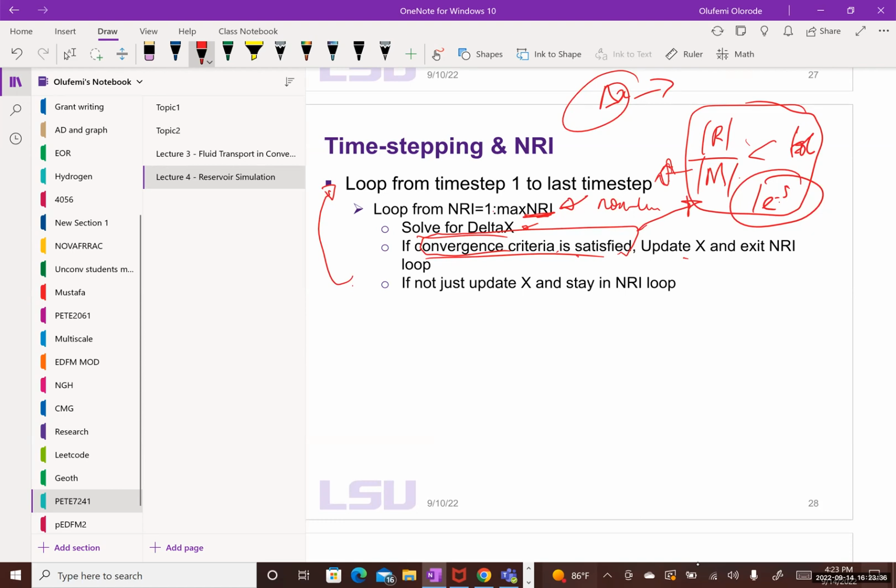So you don't know that the system converged and you're moving to the next time step. It may not converge in 4 iterations, and then your error can blow up and you start getting garbage in your code. So you have to make sure it's actually correct. That you went 4 iterations does not mean it's okay. And if you change it to 12 so that you can guarantee it to converge, then you're wasting time, right? So you really need to have this in there.